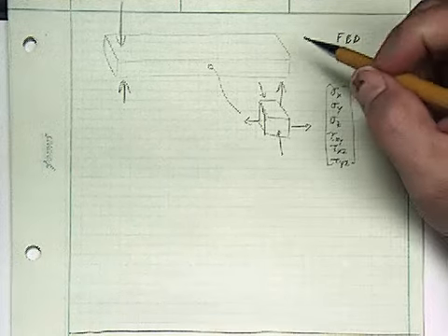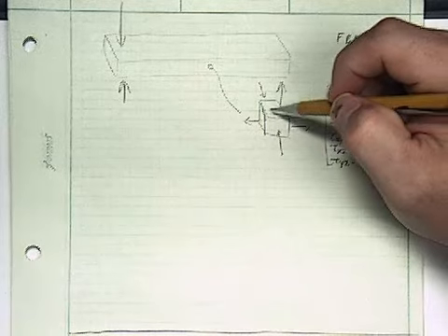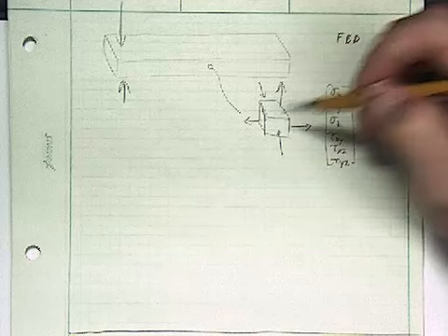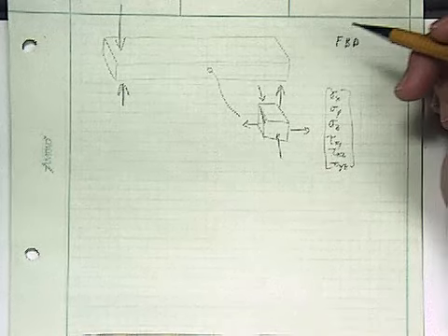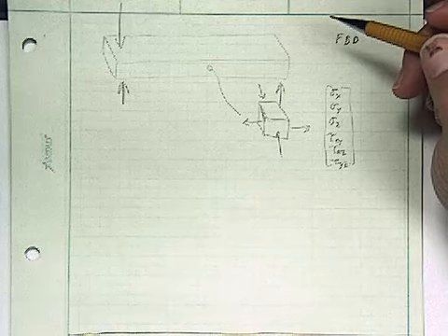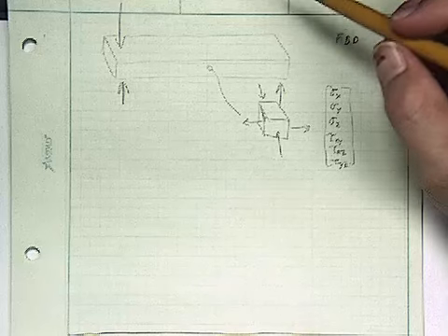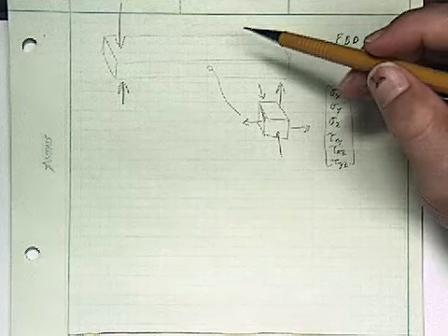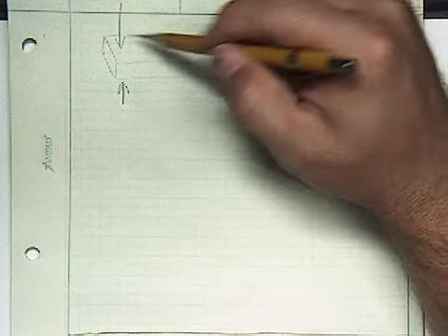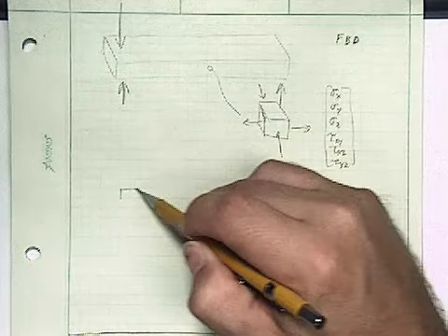So the next question we need to ask ourselves is, with a given loading condition, how can I calculate what the individual elements of the beam are experiencing? There are several different methods to do it. In this lesson, we're going to be discussing using the free body diagram as a method of actually calculating what the stresses are. As a comment going into it, my first analysis is going to be a fairly simple one. We're going to consider this beam to be identical in the third dimension. In other words, I can express the beam maybe something more like this.